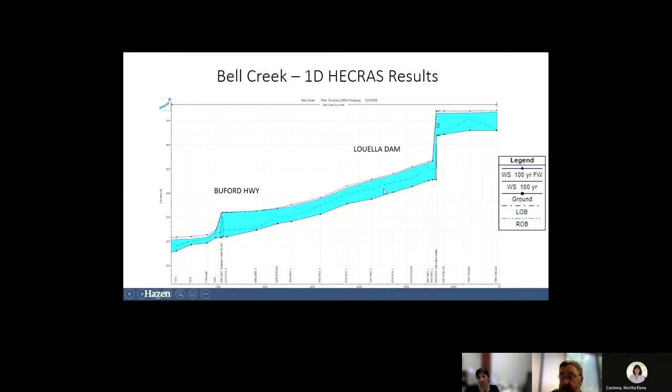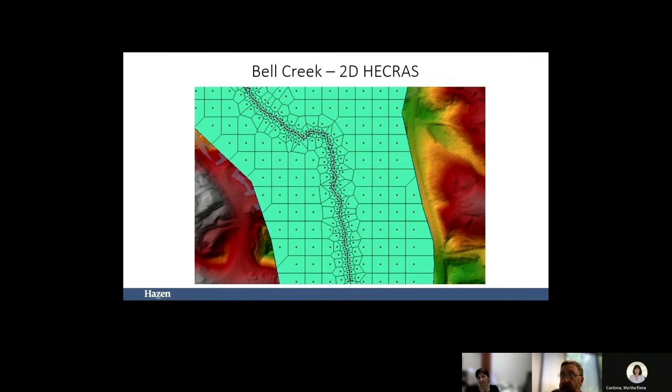So relatively, like I mentioned, a steep tributary, 0.005, steep relative to FEMA conditions, draining down to Buford Highway. Two-dimensional HEC-RAS, fairly straightforward grid pattern, merging geometry within the channel to the overbanks and using LiDAR data information in order to perform that geometric development.